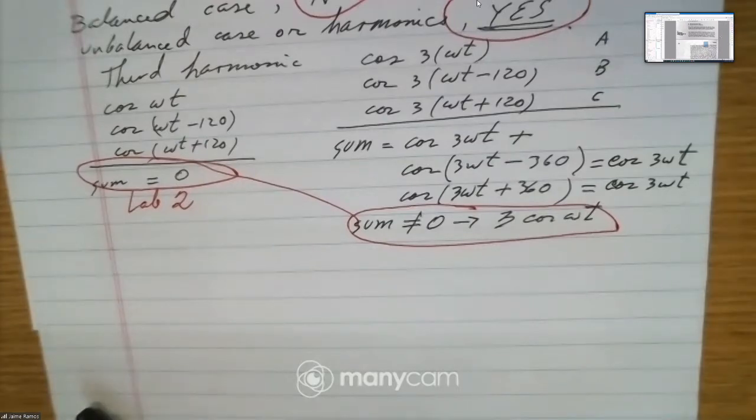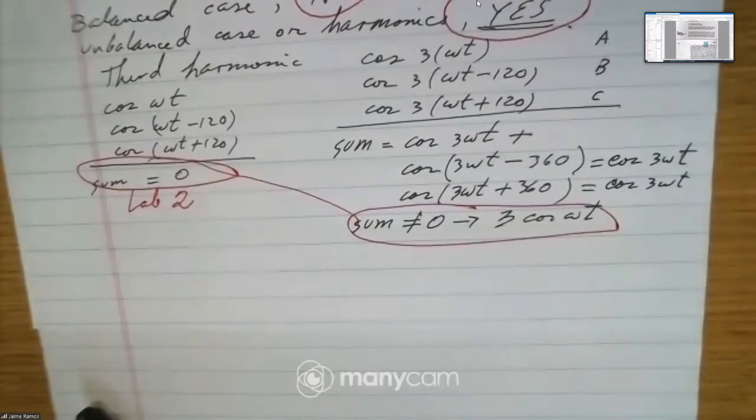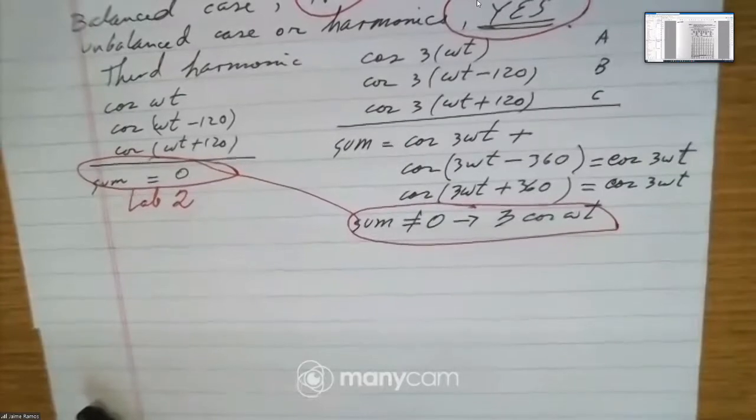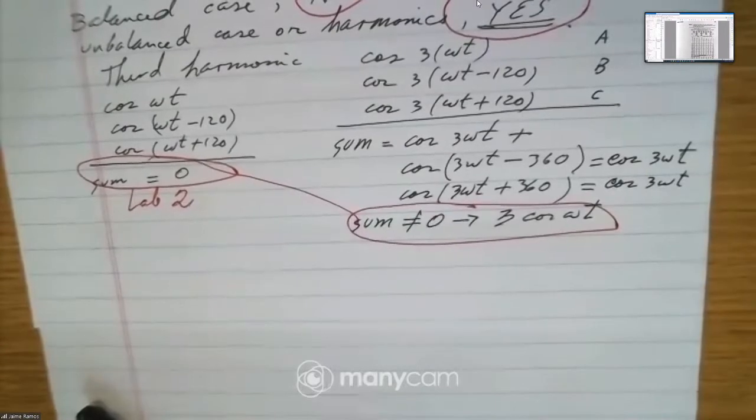Okay, so page 343. Let me go to page 343 here. Okay, 343 right here. So here is this table. Look at the heading: Ampacities of not more than 3 single insulated conductors. So this table is for 3 single insulated conductors.